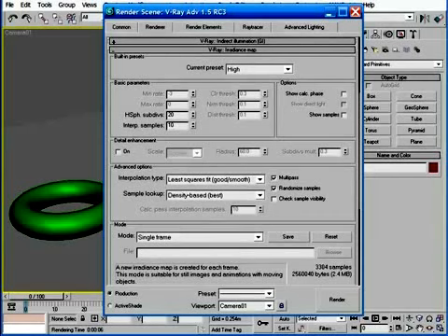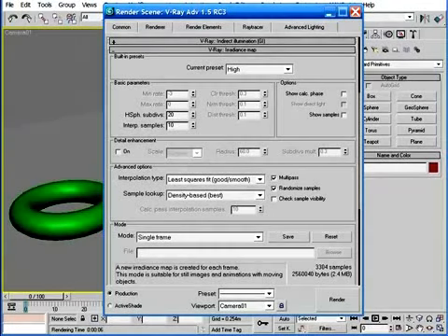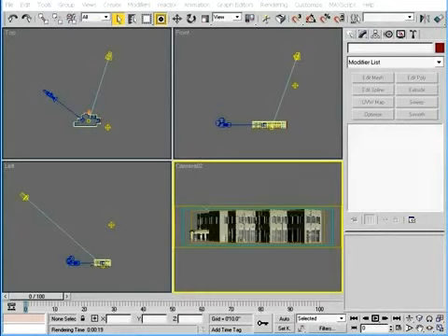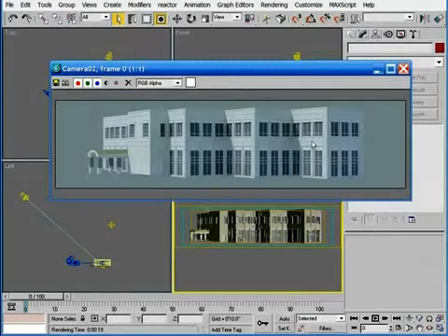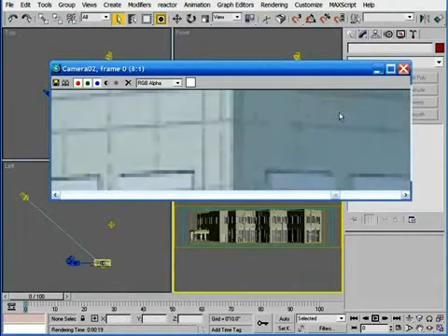And to see just what effect this has versus other settings, not only in the irradiance map but other settings in VRay, let's walk through a sample exercise. If you want to follow along with this exercise in Max, you can open up the file called building01.max. Now, if I render the scene as is, you'll see that there is a significant amount of detail lost in the reveal lines and in the grout lines of this building.